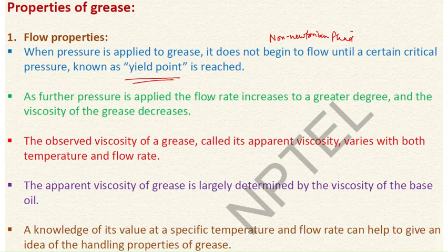As further pressure is applied, the flow rate increases to a greater degree, and the viscosity of the grease decreases. The observed viscosity of a grease, called its apparent viscosity, varies with both temperature and flow rate.